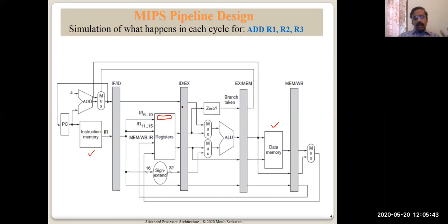They are not restricted to only a few bits; there is a limitation, but it is much more than a 32-bit value. It is capable of holding more values. This pipeline register also carries data which is being exchanged between the stages, as well as some control signals.